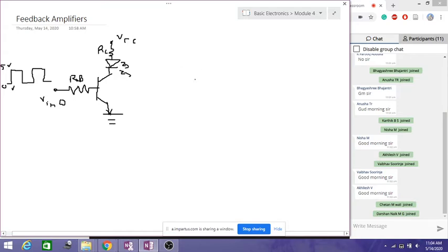What is the main criterion for the LED to turn on? For the LED to turn on, its anode terminal, this is the anode terminal and this we call the cathode terminal, should be connected to the positive voltage. It might be plus 5 volts or plus 10 volts through a current limiting resistor. I have not written a current limiting resistor. And the other end, the cathode, should be connected to ground. If the transistor is like an open switch, it means this ground path is disconnected, so the LED is not on and remains in the off state.